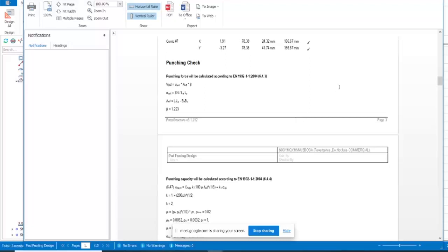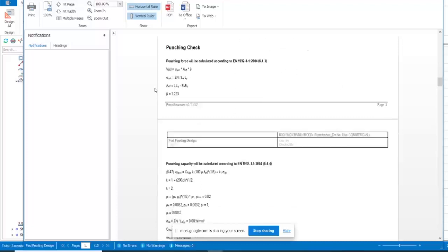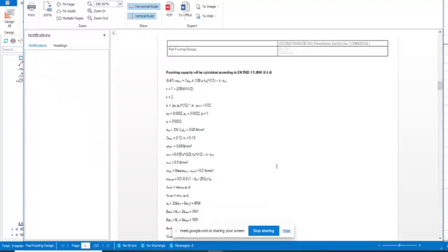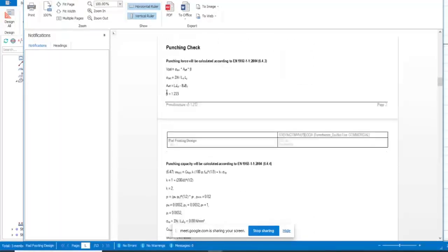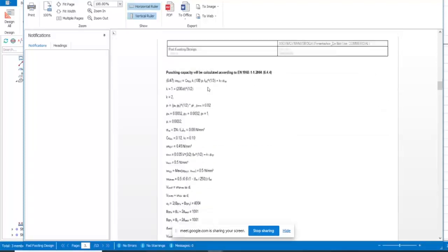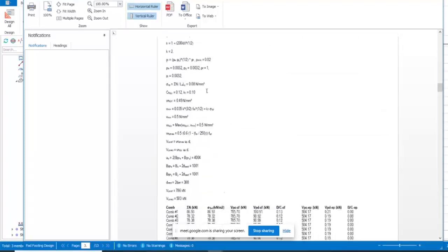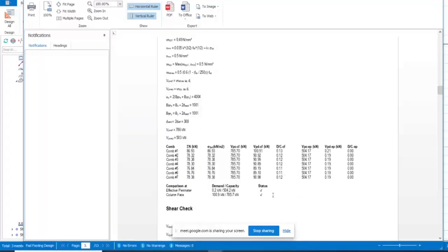All right. So what are the things we would most likely prefer as solutions to a punching effect, either to prevent it or to stop it? What are those things you do? You can see my calculation for punching check here. Take 1.5d and you design for punching shear.